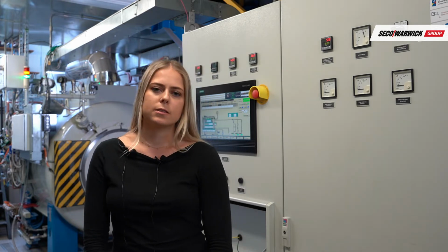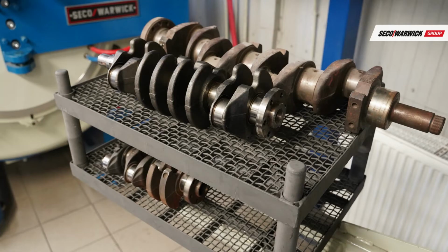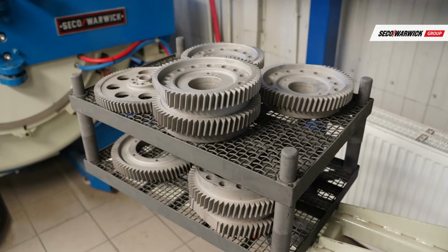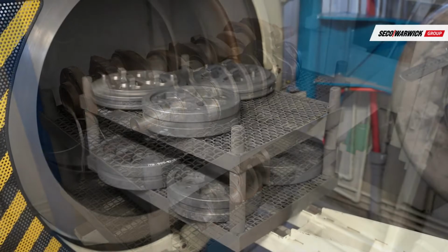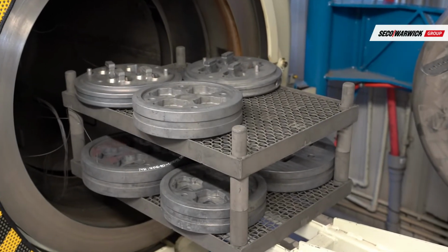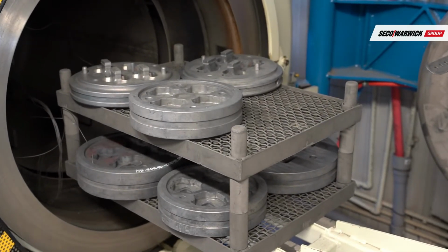Nitriding is a thermochemical process in which the surface of machine parts and tools is enriched in nitrogen. In high temperature processes in an atmosphere of ammonia, a surface diffusion layer of improved tribological, anti-corrosion and wear resistance properties is being created. Elements that undergo this process are mostly parts of machines and vehicles, such as crankshafts, gear wheels, camshafts, piston rings, valve discs and nozzles, as well as tools like molds and drills.